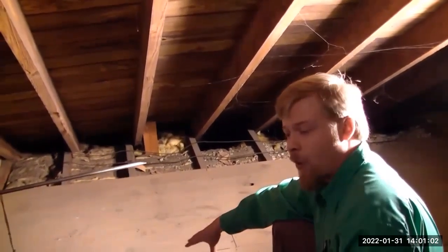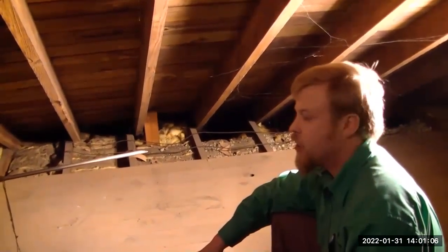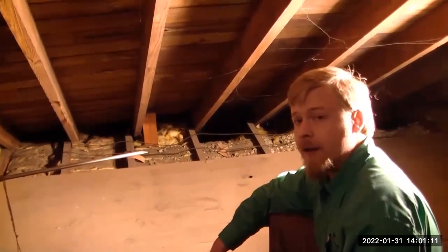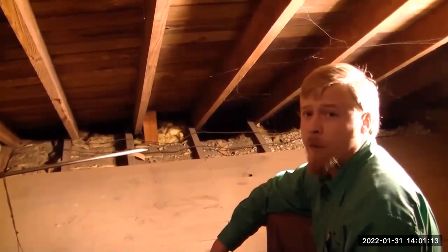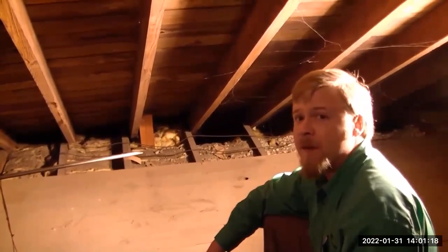Now, they've actually floored in here, so we have a maximum of about 6 inches of insulation in this attic space. In this area that we're in, you actually want to be at around an R49 value. So we're going to need to add about 12 to 15 inches.